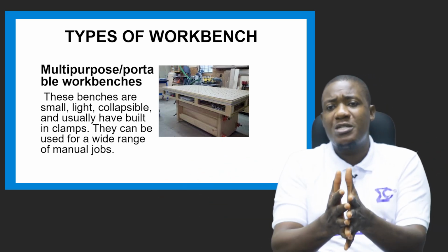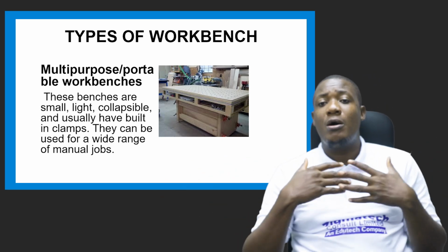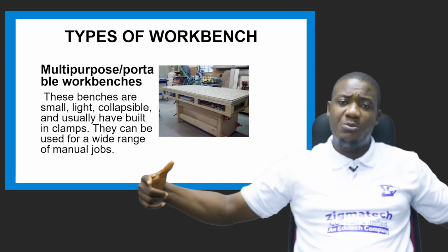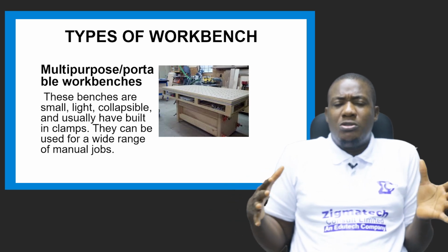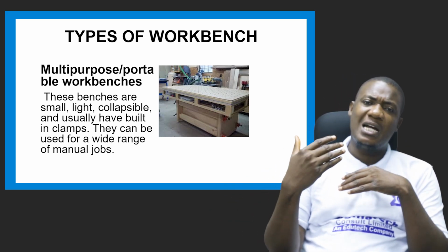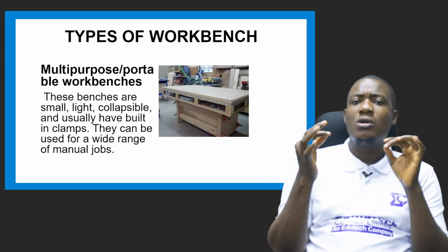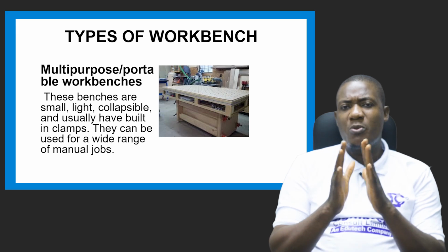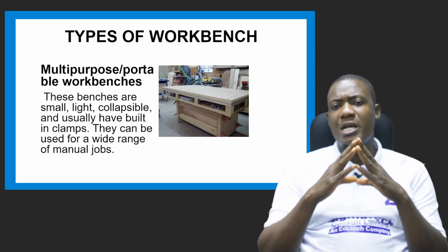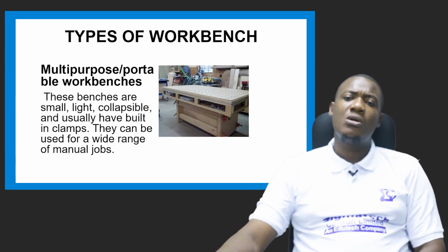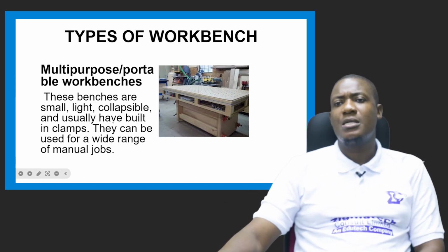Basically, when you want to join pieces of wood together, let's say you want to fabricate a door, for example, it is the F clamp that will help you to hold the pieces of wood after you've applied adhesives or you just stack them. Normally, at the end of it, you see the workpieces glued together like that. So that's the major function of the clamps.